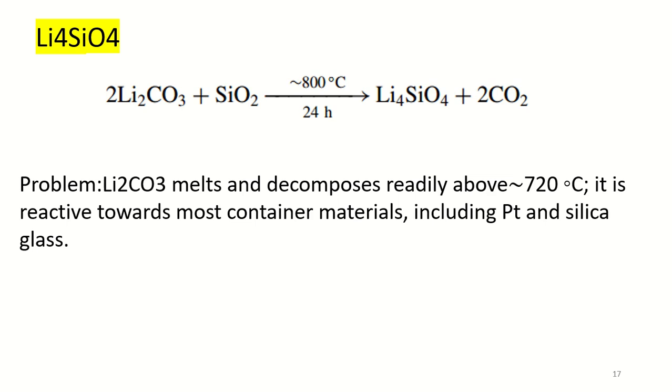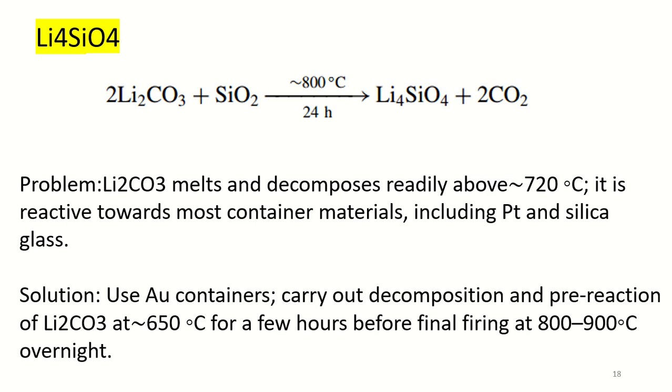The solution is that we should use gold containers, carrying out decomposition and pre-reaction of lithium carbonate at 625 degrees Celsius for a few hours before final firing at about 900 degrees Celsius overnight.